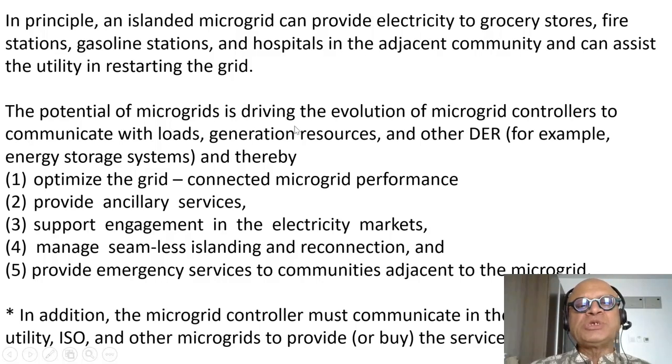The potential of microgrids is driving the evolution of microgrid controllers to communicate with the loads, generation resources, and other distributed energy resources, for example energy storage systems, and thereby optimize the grid, provide ancillary services, support engagement in the electricity markets, manage seamless islanding and reconnection, and provide emergency services to communities adjacent to the microgrid.